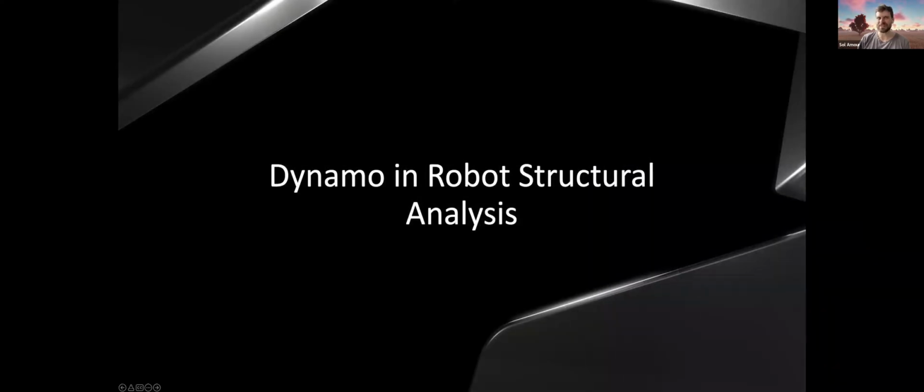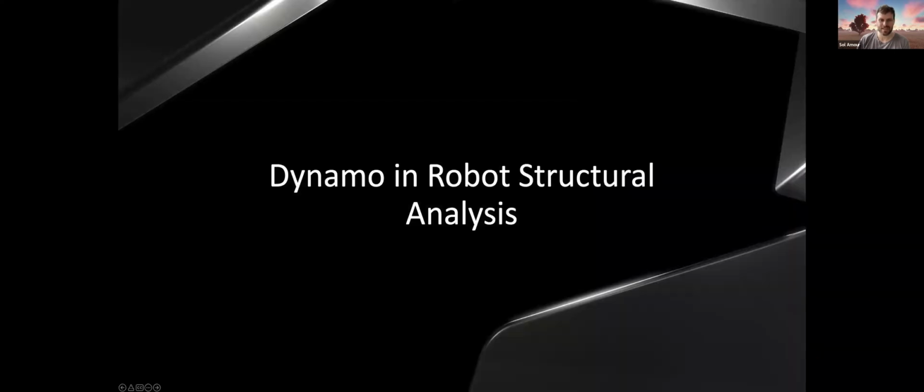We can stop that. So you'll notice that in the FormIt world here, if I go back one hot second and pause this, well, okay, it's not going to happen. But you'll notice that essentially, if you have a group that has created geometry inside of Dynamo and FormIt, that group has those properties and will update based on context. So if you have a series of different graphs that are dependent on a series of different groups, creating a series of different geometry, and you run those again in sequence, it's going to update those in the process. So what you noticed was we changed the floor plate, that then subsequently changed the glazing, that then subsequently changed the facade louver system as well.